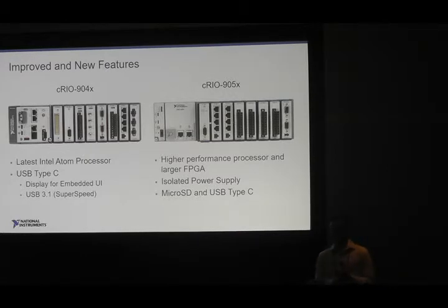One of which I've already talked about, the micro SD a little bit in the USB Type-C, so I won't hit that too much more. But one thing I do want to call out here is we've added an isolated power supply for this low-end variant. It's something that we had on many of our higher-end CompactRIO controllers in the past to help protect the system a little bit more from maybe improper wiring or some things that may come up that cause potential issues going through the power supply.